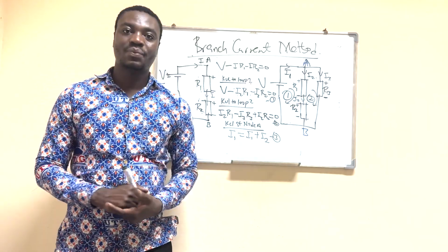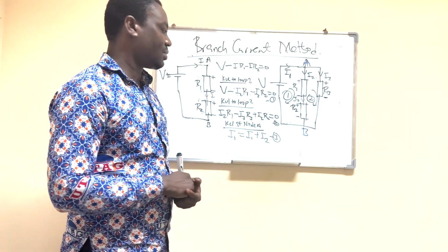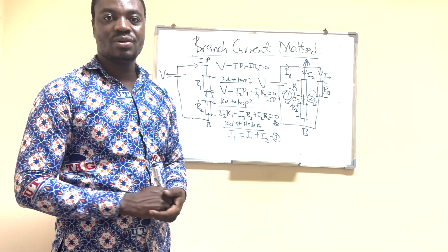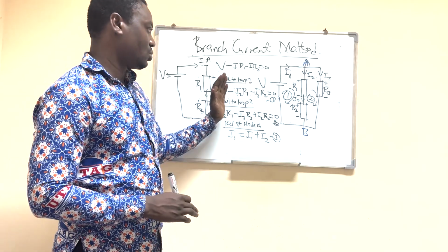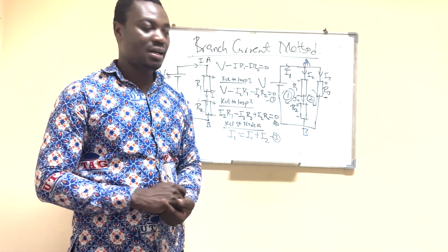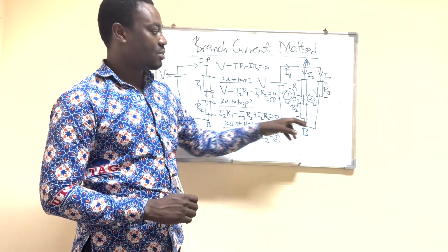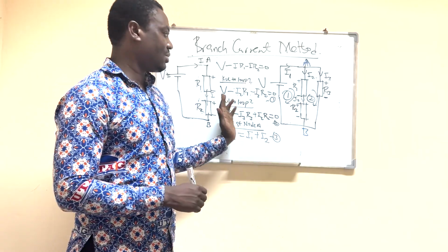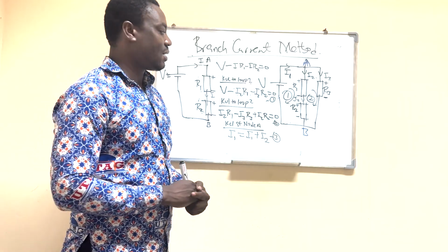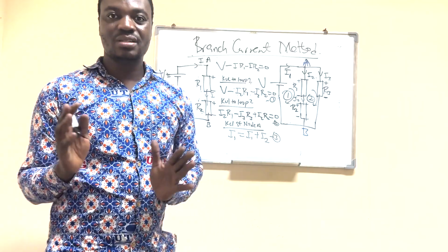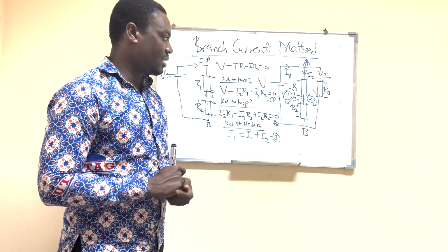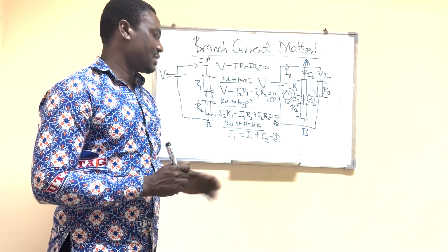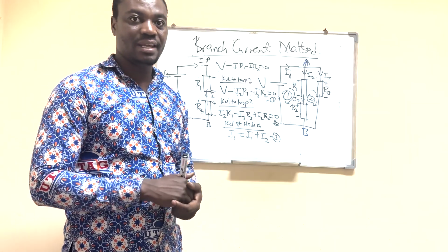Now we go to the third step, which is to write the equations by applying Kirchhoff voltage law to the loops in the circuit diagram. So here I have 2 loops. Actually, we have 3, but 2 is okay, right? Because you can see we have 3 variables, while I need 3 equations to solve for the 3 variables. So if we have 2 loops, using these 2 loops, then after that, I'll apply Kirchhoff current law. That will give me the third equation.